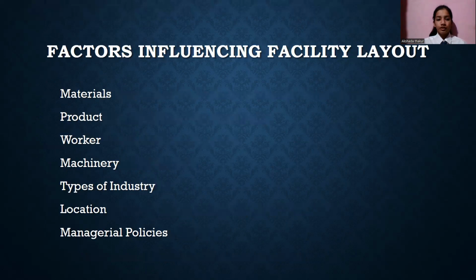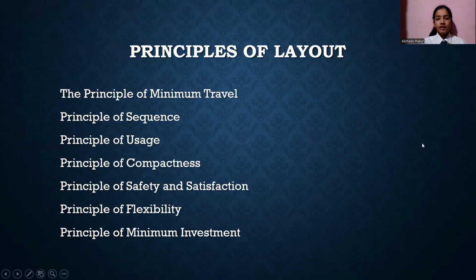Factors influencing facility layout: material, product, worker, machinery, types of industry, location, managerial policy. Principles of layout: the principle of minimum travel, principle of sequence, principle of usage, principle of compactness, principle of safety and satisfaction, principle of flexibility, principle of minimum investment.